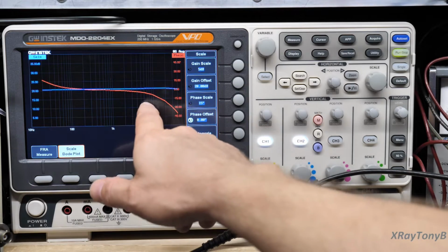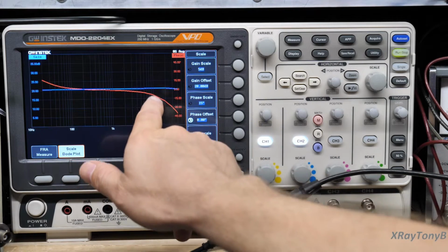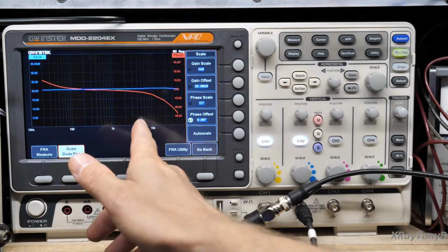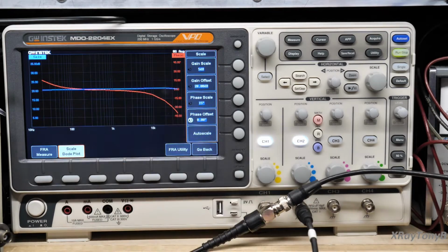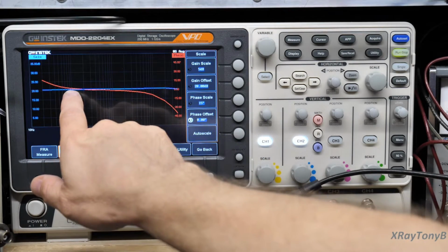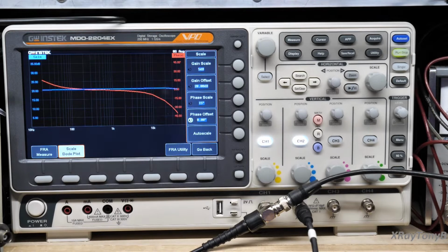But we do see that somewhere around 3 kilohertz, it starts shifting the phase, and back here at 100 hertz, it starts shifting the phase in the other direction. Now, this is a function of this amplifier. And notice there are no tone controls in there. But you're going to find that a lot of amplifiers will do this. So let's now adjust the tone control and see what happens.